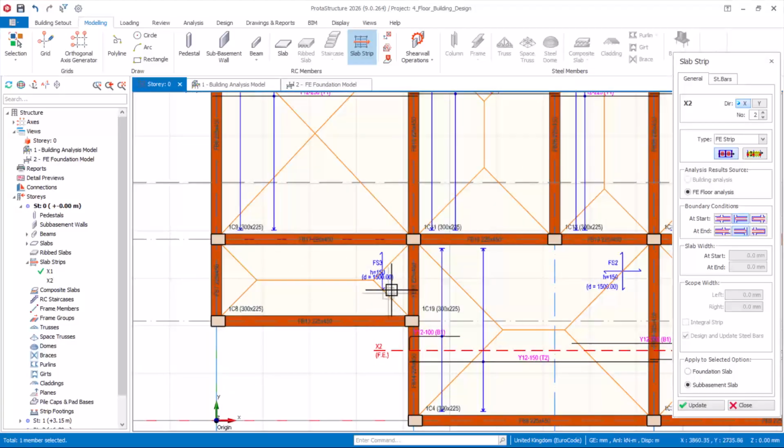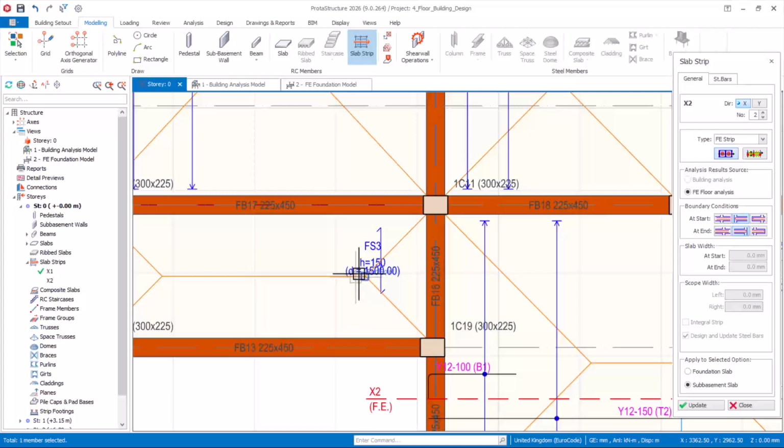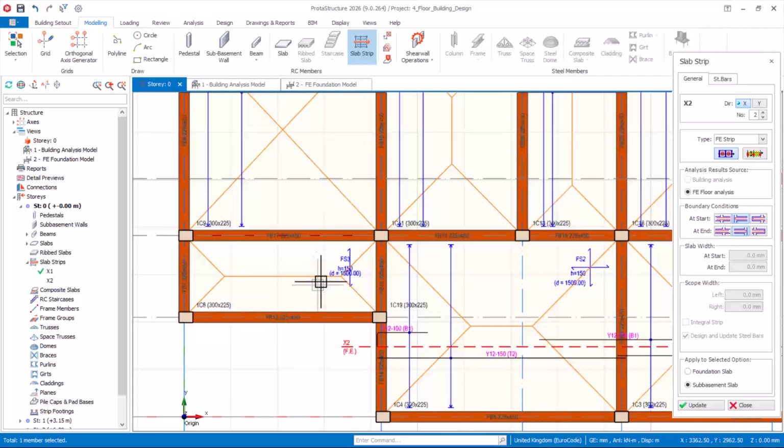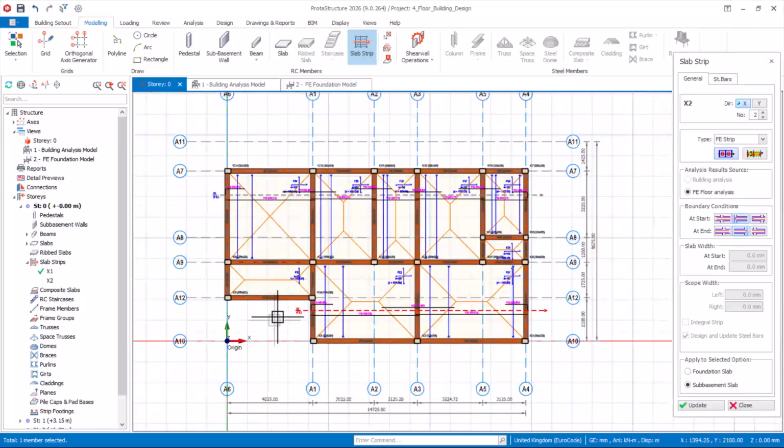All right. So what you need to do here, increase the thickness right here, but this is resting on the soil. You don't really need to increase the system because this is not suspended. All right. So what you just have to do, leave it the way it is. It is resting on the soil. It's already supported by the soil all through its area. All right. Unlike the suspended floor.